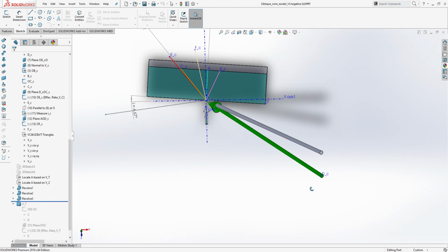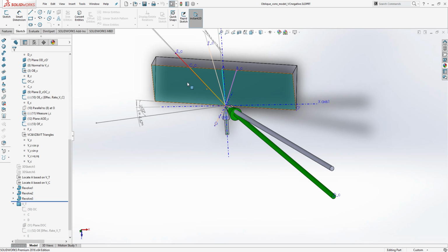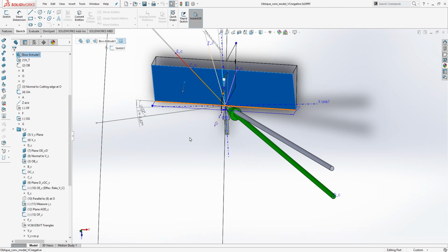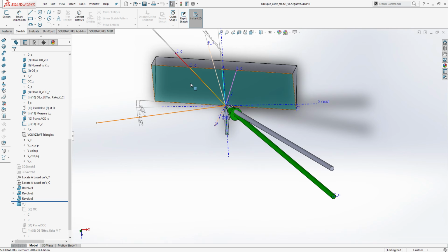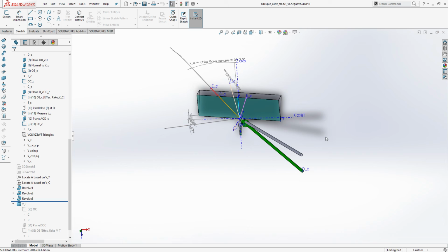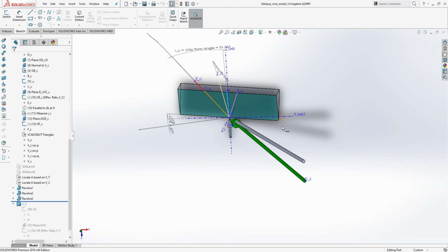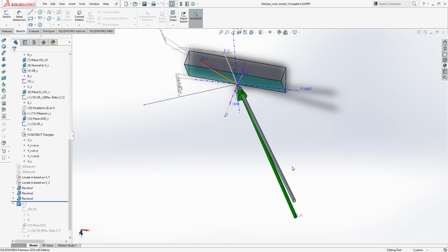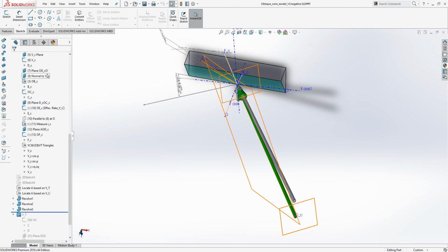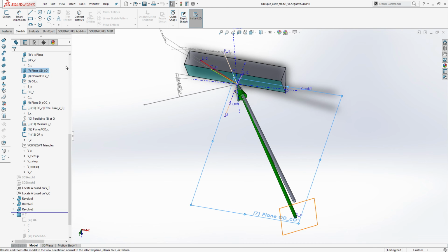And if we see that, the rake angle will be negative. But the inclination angle will be changed from the previous value. So maybe I will see from the top view of this.